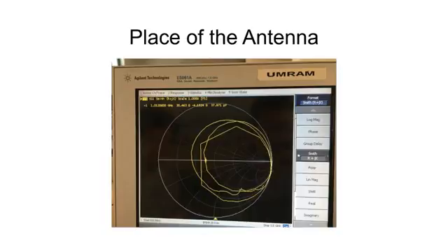I have used many locations, but the best I could get is the location that I showed you before, because in that location I got 35 ohm of resistance, which is the closest I could get to 50 ohm, where 50 ohm is the impedance of the signal generator.